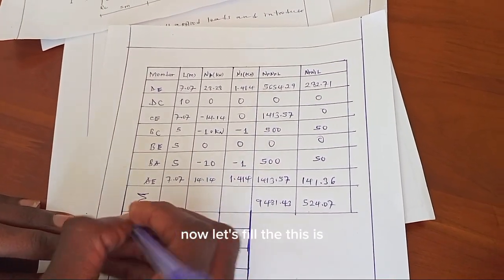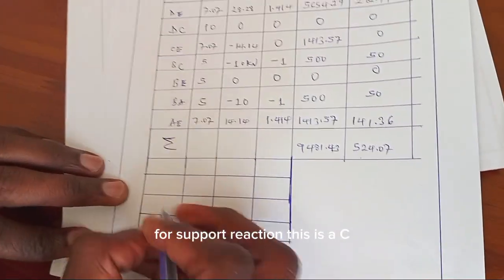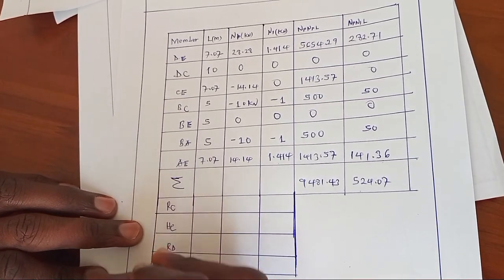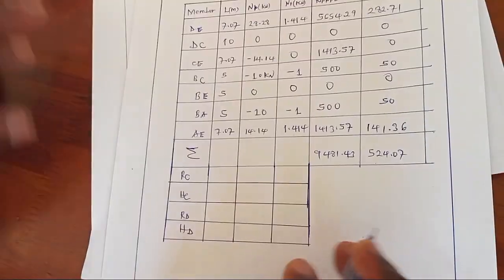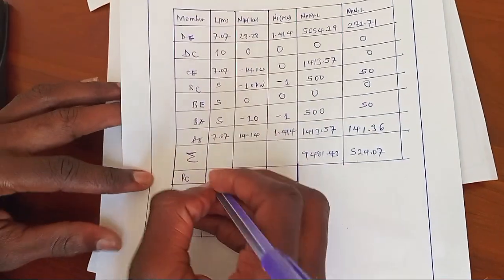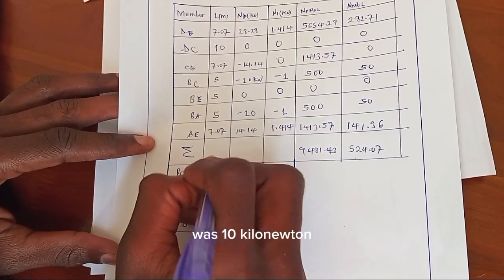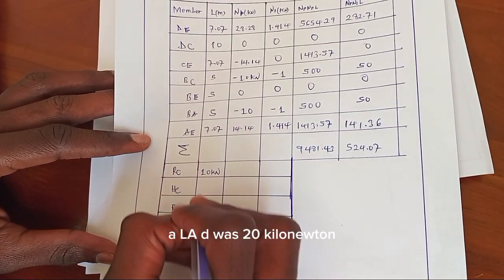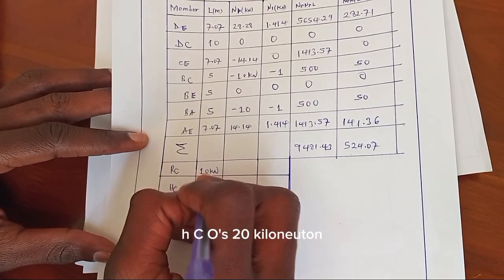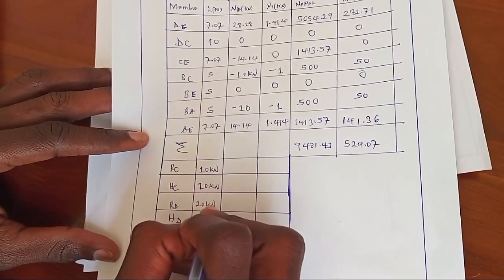Now let's fill this in. This is for the support reactions: RC, HC, RD, HD. RC was 10 kilonewton, RD was 20 kilonewton, HC was 20 kilonewton, HD was negative 20 kilonewton.